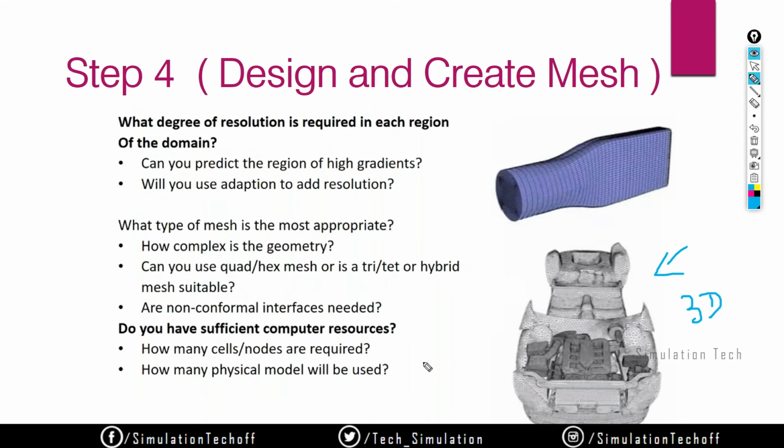So a component like this, you only solve by using servers, not on laptops. Server-based solvers are used to execute big problems having lakhs and lakhs of nodes. Even a server takes 3 to 4 days to solve the problem, and again it may show an error, the problem is not converged, and then you have to work again. So that is why I am saying make sure you have sufficient computer resources.